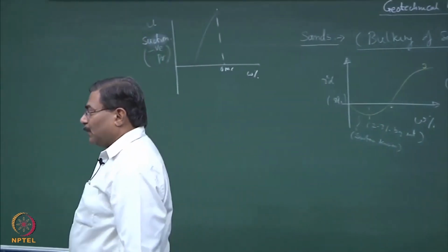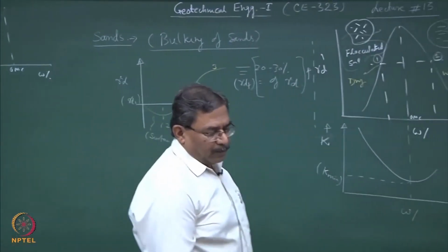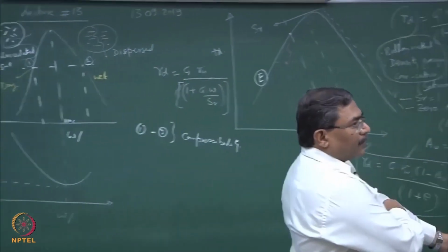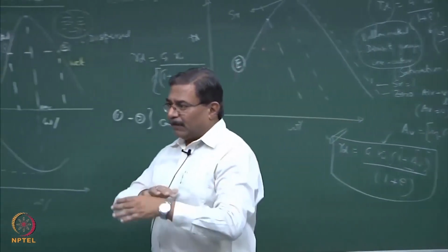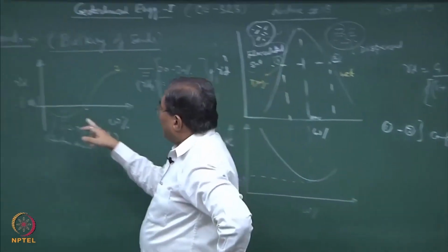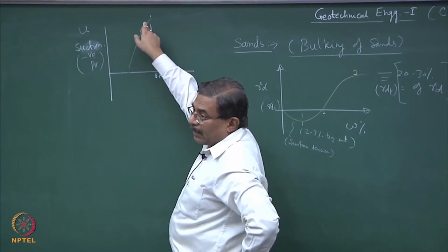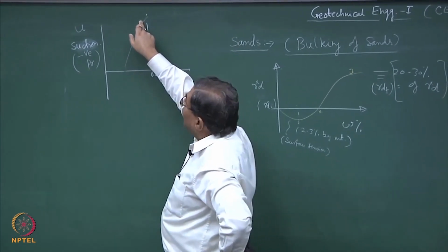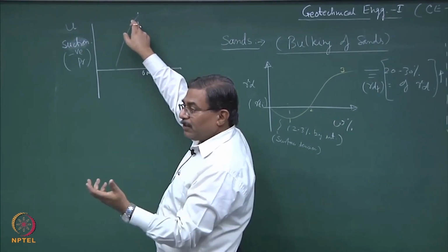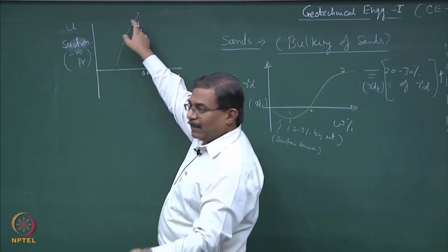These type of situations are going to be extremely problematic. You imagine every year in Bombay city, the tracks get flooded during rains, all right. So, imagine that you have created an embankment, rains come, water logging takes place, and close to OMC, you have maximum suction which is getting developed in the system. Given a chance, because of this suction, the tendency of the material would be to suck most of the moisture which is available freely, and hence the soil mass beneath the track becomes wet.